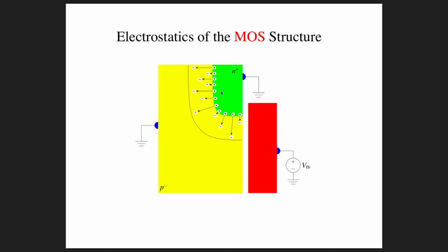Okay, so electrons in this N+ region would want to diffuse into the region of relatively low electron concentration in the p region. Likewise, holes, which are relatively plentiful in the p region, but relatively poor in the n region, would want to diffuse this way toward the region of low concentration.